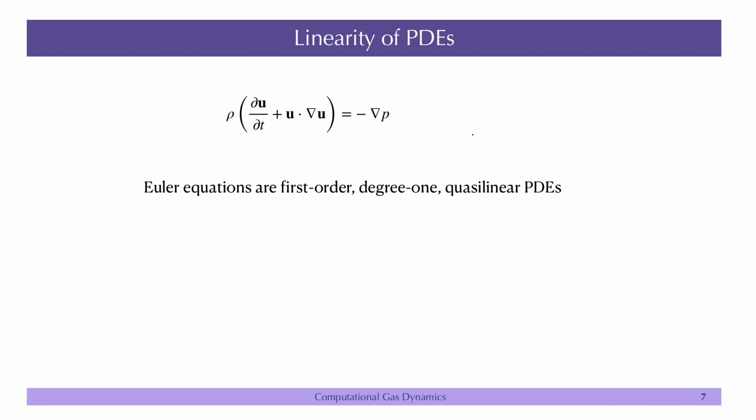So, if you look at, for example, the Euler equation, what is the order of the Euler equation? There is no viscous term there, right. So, there is no del dot tau term, or basically the tau itself goes as something like du by dx, right. So, it is basically a second order term, and the second order term is missing there. So, this equation is first order, okay, and the first order term has got first degree.